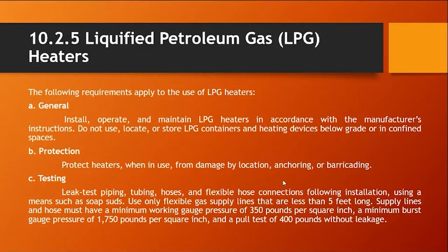Next is for liquefied petroleum gas, or LPG, heaters. In general, install, operate, and maintain LPG heaters in accordance with the manufacturer's instructions. Do not use, locate, or store LPG containers and heating devices below grade or in confined spaces.